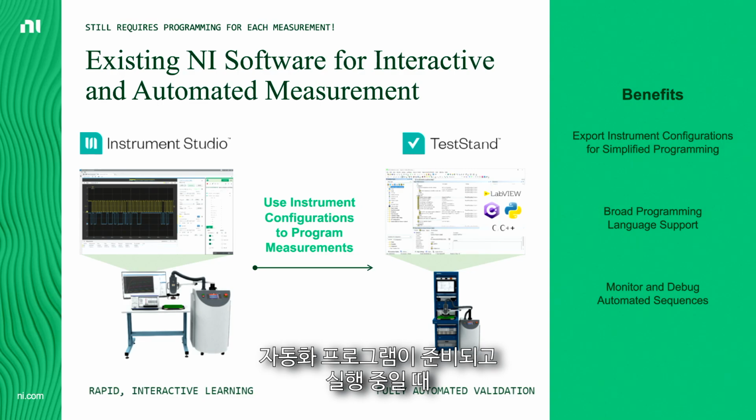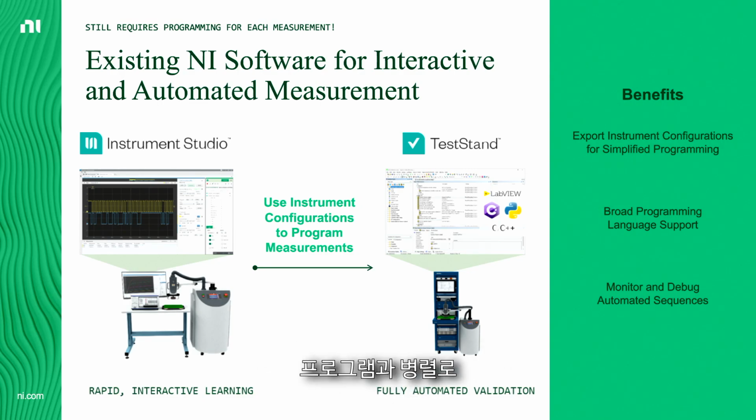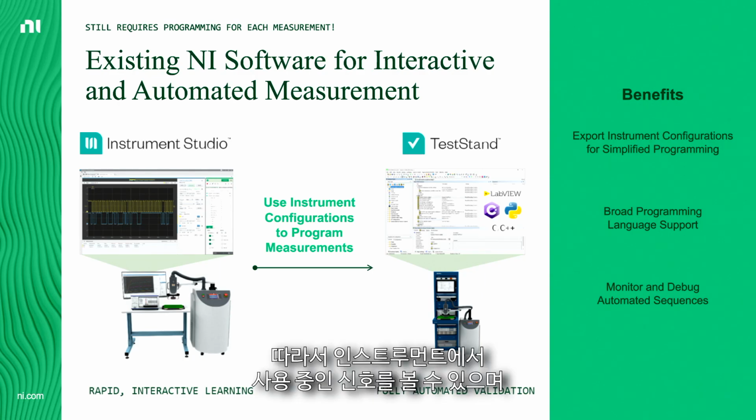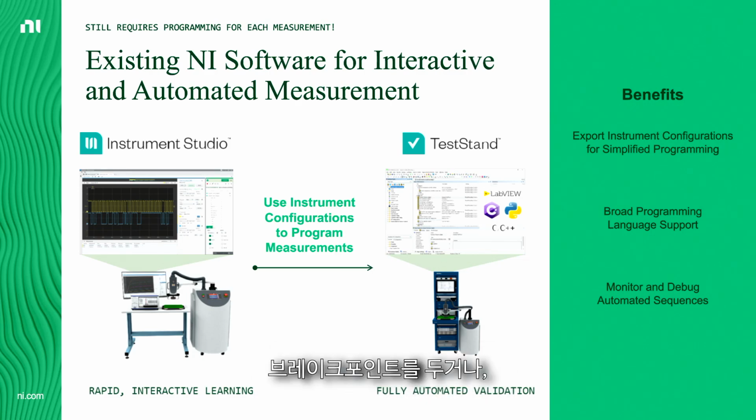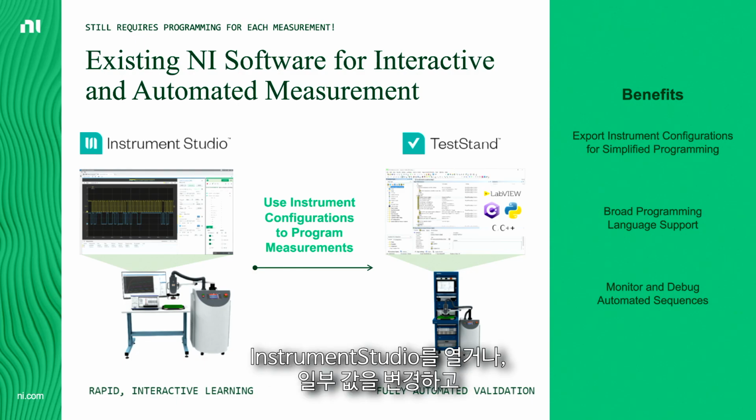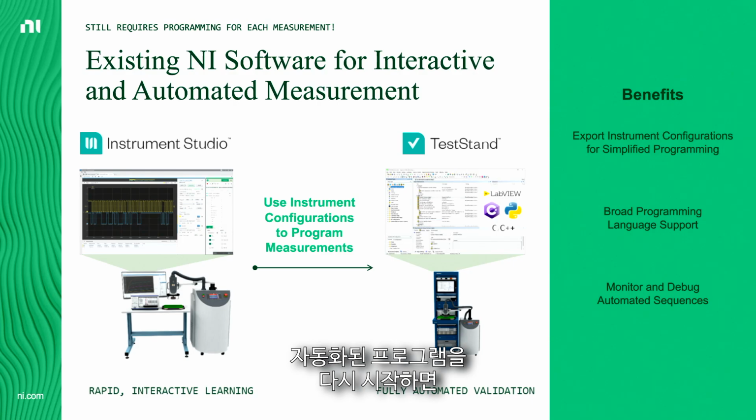And when the automated program is ready and it's running, you can actually use Instrument Studio in parallel with your automated program for monitoring and debugging. So you can see the live signals from the instruments, and then if something seems wrong, you can pause your program or place a breakpoint. You can open up Instrument Studio, change some values, and then start your automated program again, and those values will persist into your automated program. So it's a really, really powerful tool.